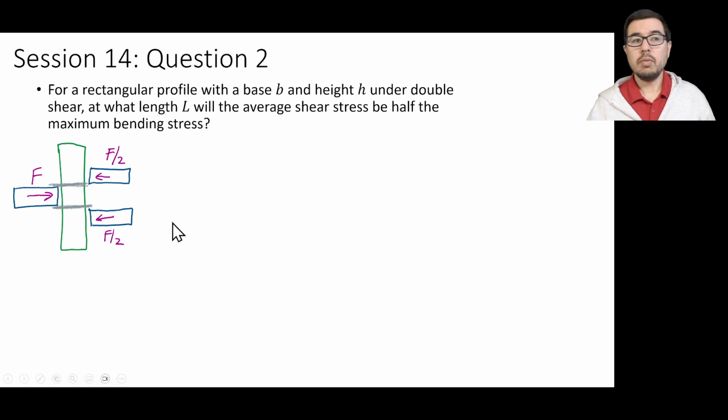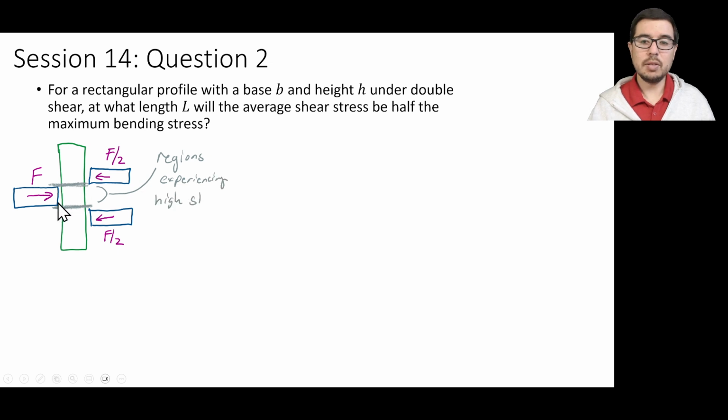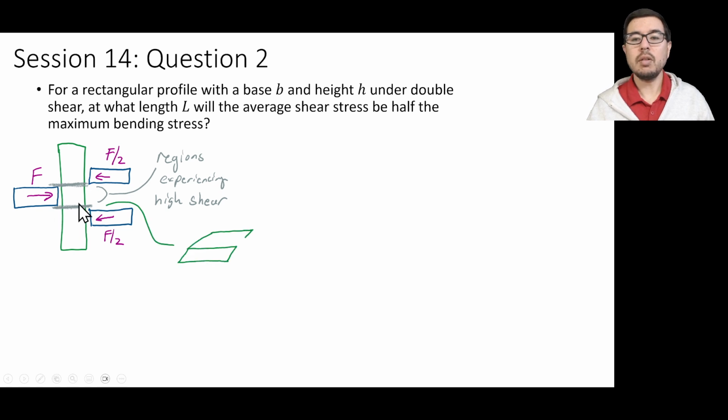The region experiencing shear is given by these grayed out pencil-like lines. As we've described previously, if you get into this interface, you would see that it has an area and there's a shear stress acting on that area. The area would be into the plane, with the width given by the width across the pin.